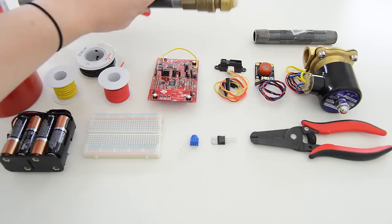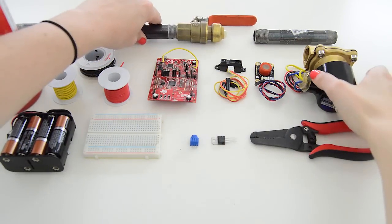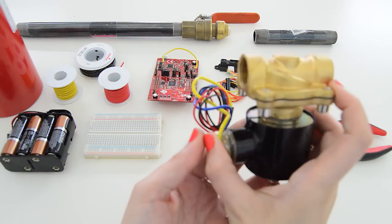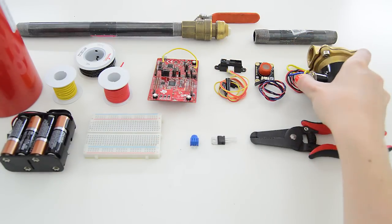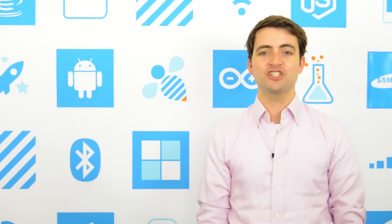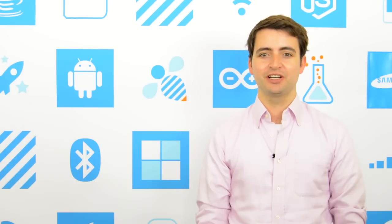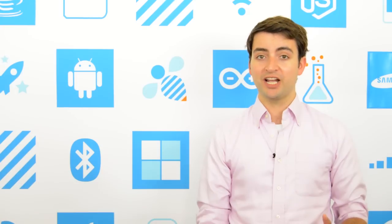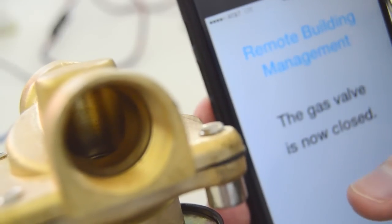We've replaced a manual gas valve with an electric solenoid valve that can be remotely opened and closed from an iOS app. When this electrochemical sensor detects a carbon monoxide leak, our Texas Instruments CC3200 board will send an Amazon SNS notification to the building manager. The building manager can then remotely close the gas line from the iOS app using an Amazon SQS queue that is read by the board.